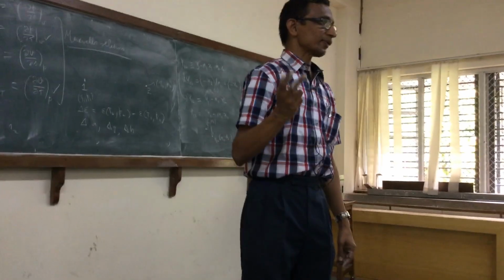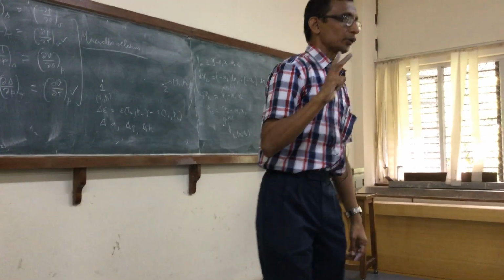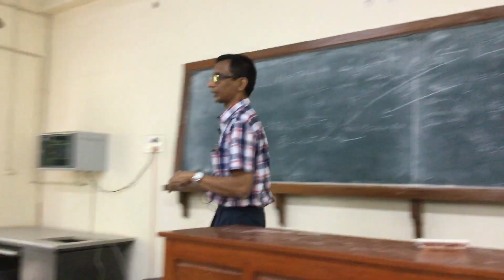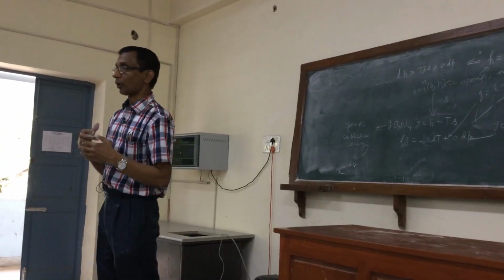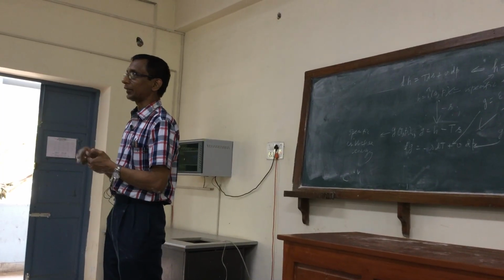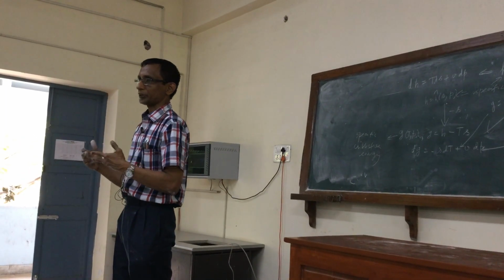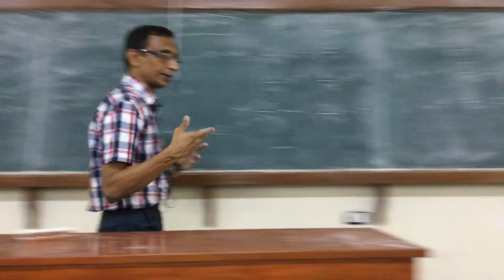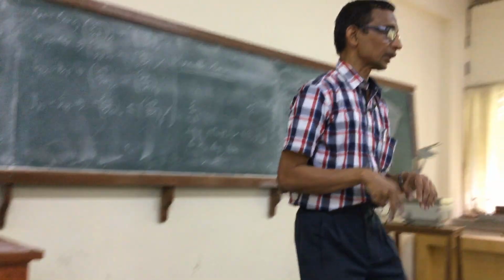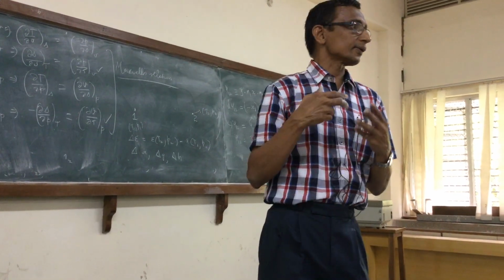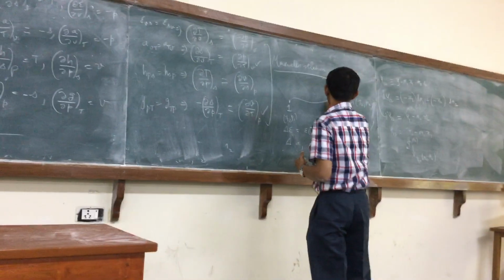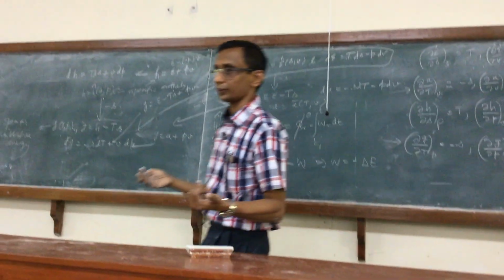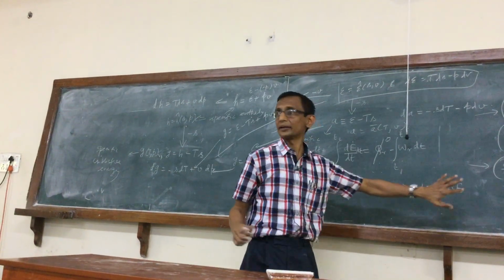So you have to see the significance of this. Normally, when you're talking about work done, the only case where you might have calculated the work explicitly is when the body undergoes a reversible process. Then you can simply do PdV. Even that you have done for some special cases like an adiabatic process or an isothermal process. Otherwise, calculating the line integral will not be that easy. However, what this says is it doesn't matter what process it has undergone from one state to another. It might have undergone a completely irreversible process, but this formula is still valid.